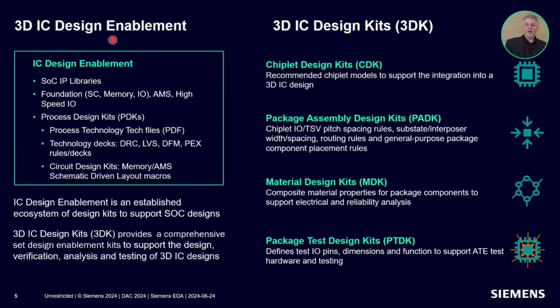Okay, so design enablement. As I mentioned, the IC design process has a very structured, well-defined design enablement. It includes IP, the building blocks used within system-on-chip designs. And we have process design kits, which include the technology rules necessary for creating extraction decks, place and route decks, etc. There are also macros supported for memory and analog signal type designs, reusable building blocks.